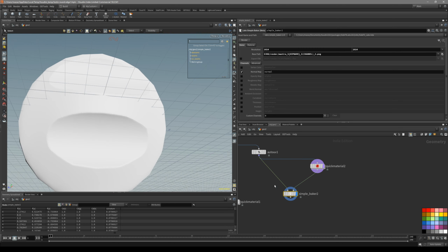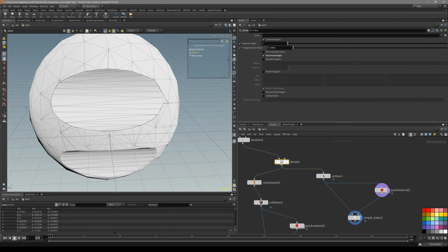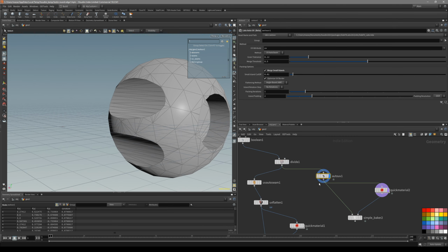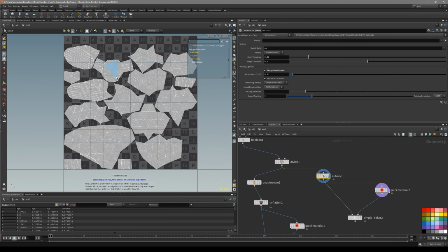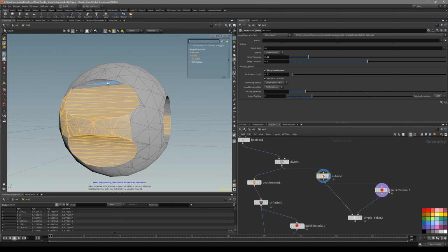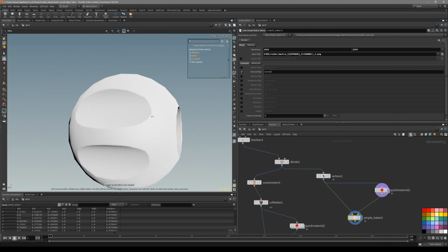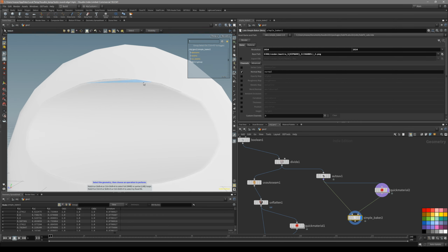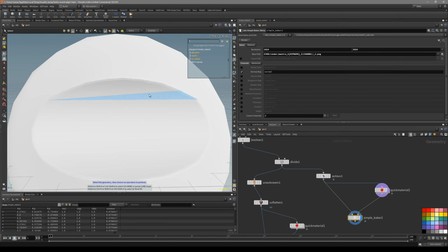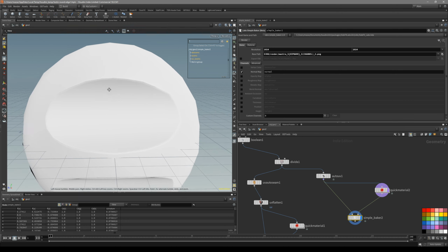And this is our second example. Basically, after I created the geometry, I put down an auto UV, and you can see we have many connected pieces that are not disconnected where we actually want our rounded edge shader. And if you take a look at this result, you can see we're getting these kind of black borders. So I can easily see where we have connected geometry.